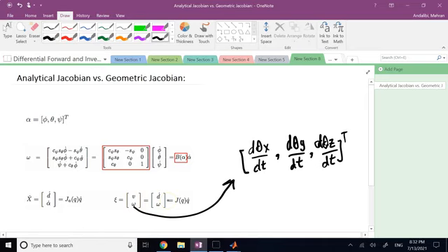And here, let's take a look. So here I assume that I have three Euler angles, phi, theta, and psi. Here the order is reversed. Instead of psi, theta, phi, theta, psi, but it does not really matter. It's just notation. So here the orientation of the end-effector frame with respect to the base is shown with three Euler angles, phi, theta, and psi.